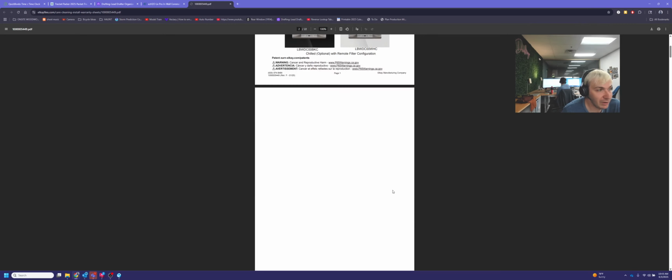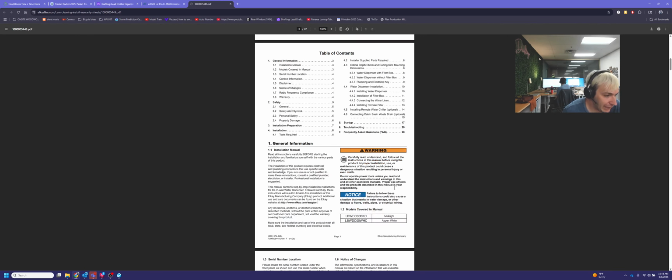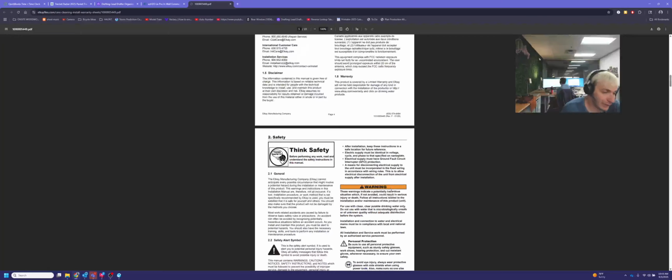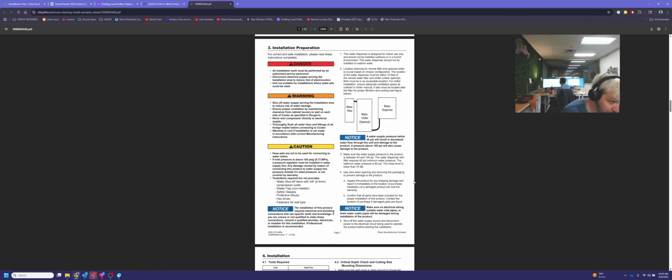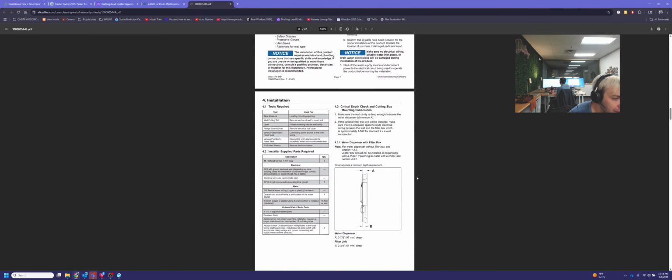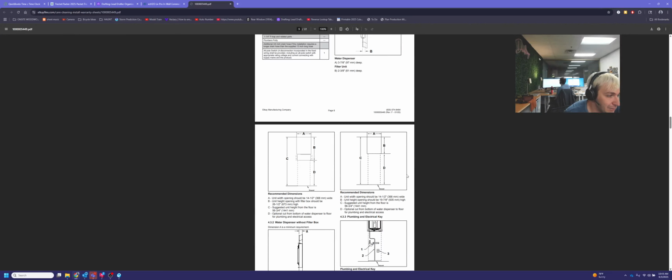Now, I can guarantee we are not going to be providing this water fountain. It'll most likely be provided by the plumber that's doing all the plumbing and plumbing fixtures for the job. But because it is cut into our panels, this is why it's important to research and make sure that we have the correct cutout dimensions here.